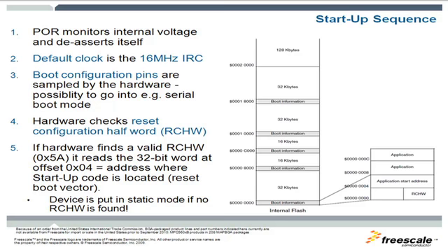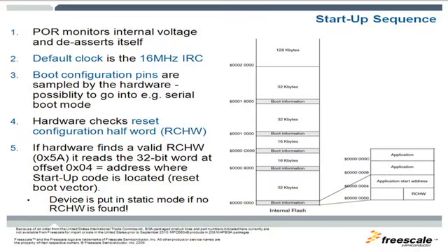You shouldn't need these. This is in case, for example, your flash is erased, there's nothing in it, and you want to program it. And it allows you to strap the pin so you can do a serial boot. You download code into RAM and then you execute from RAM. If the boot configuration says, hey, it's a normal boot, then we'll have a 16 megahertz clock, and the hardware